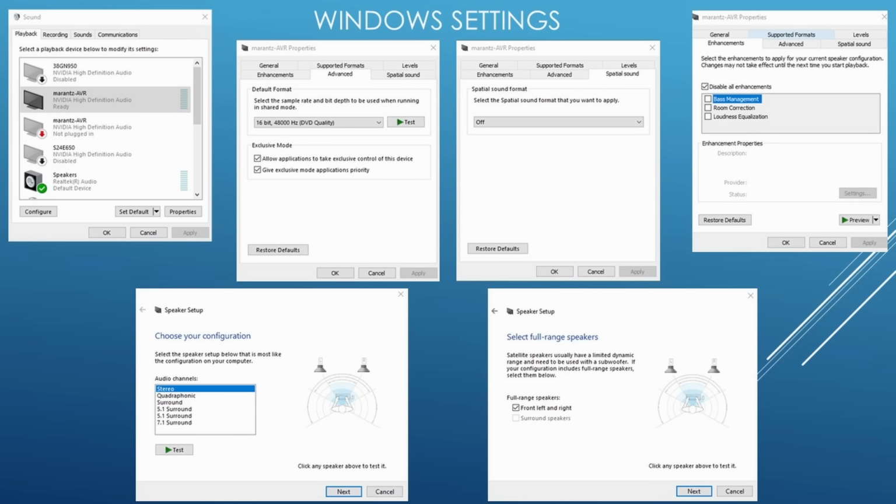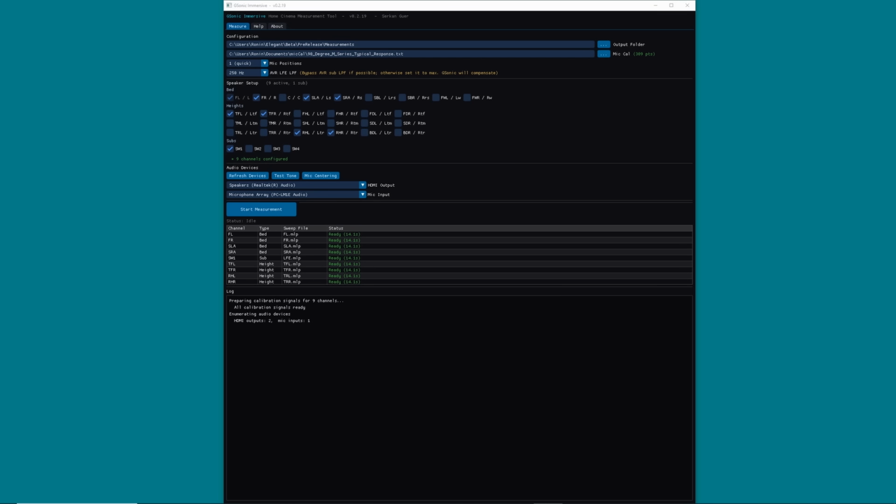If you're using a UMIK microphone, make sure it is recording at the correct gain level in Windows. If the gain is too low, you might encounter signal issues. Setting the microphone volume is something you'll need to manage within your computer's OS, as GSonic cannot control hardware gain levels. Now let's look at the GSonic app itself.